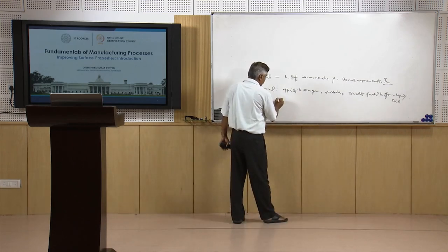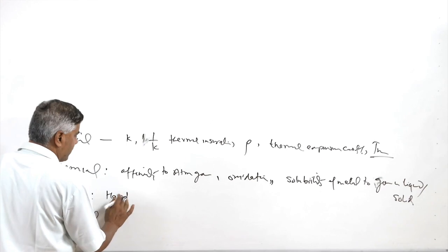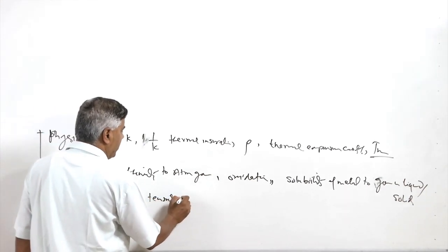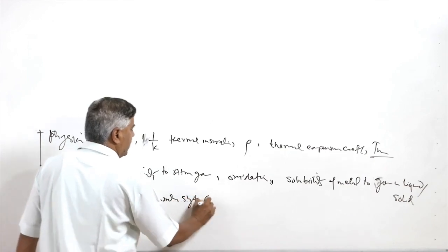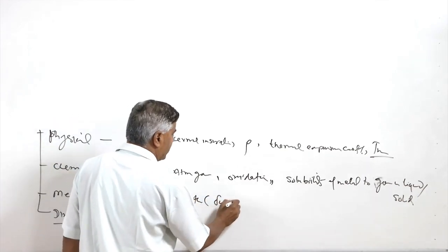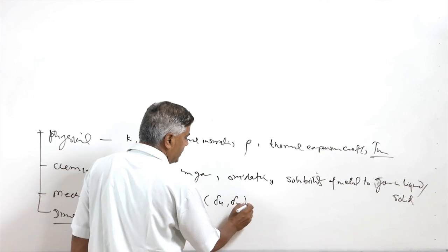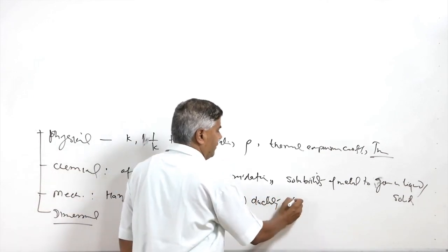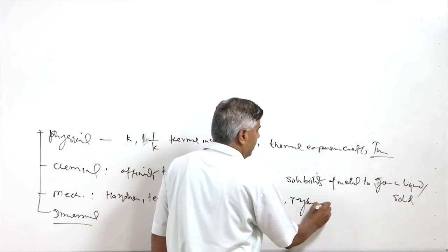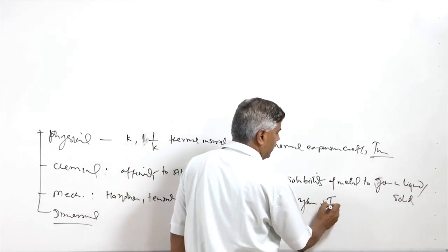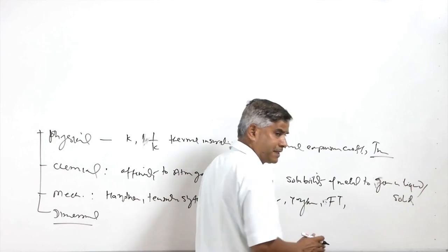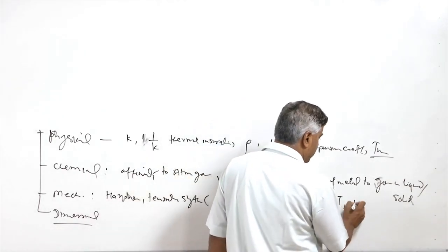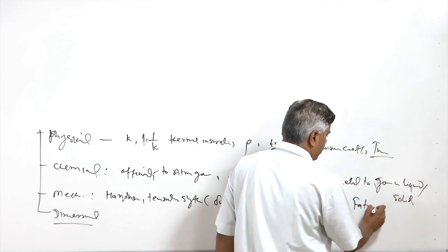The performance of the surfaces and their ability to interact with the external conditions depends to a great extent upon the mechanical properties like hardness and tensile strength, which is mainly checked depending upon the condition. It may be ultimate strength or yield strength, then ductility, toughness, fracture toughness, which shows how much resistance it will offer against crack propagation or fracture, and then fatigue resistance.